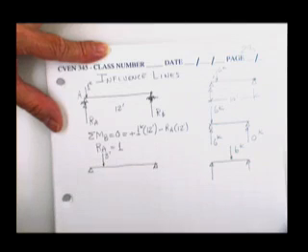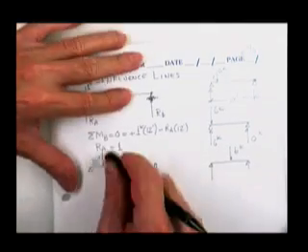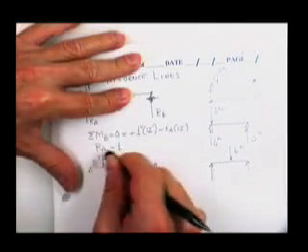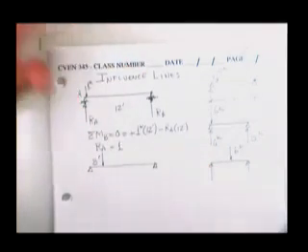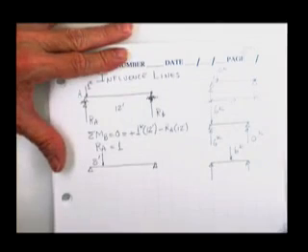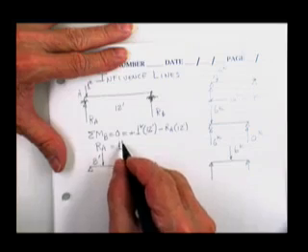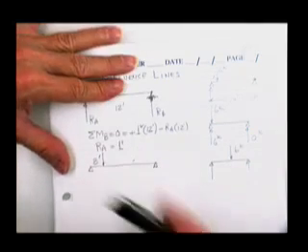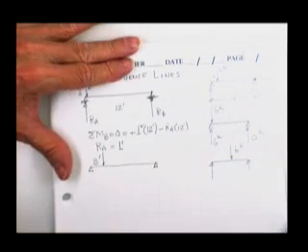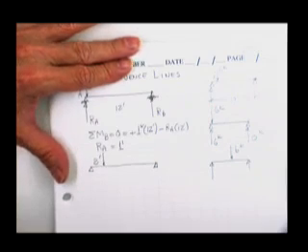I'm hoping that these points we're picking are close enough together to allow us to draw a smooth curve and be able to pick any value off of this curve that we would like. The reaction, 12 minus x. You can do an equation, yes. And then you have to plug x in at different points to plot the curve. As a matter of fact, the book likes the equations for the influence line. So either way is fine. I think they give you about the same amount of work.